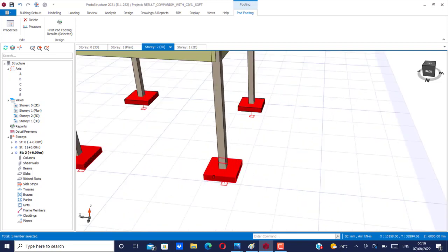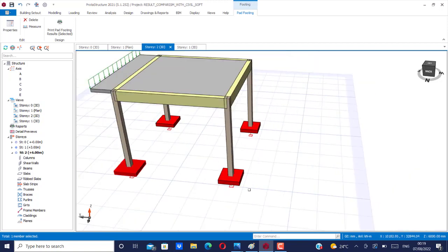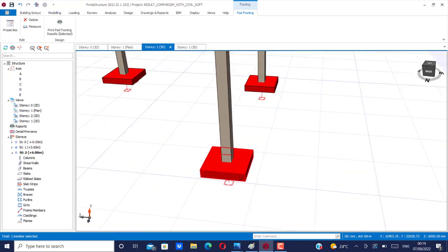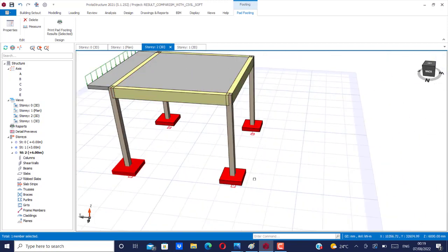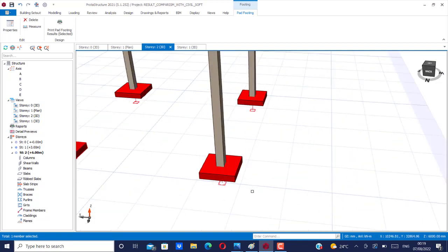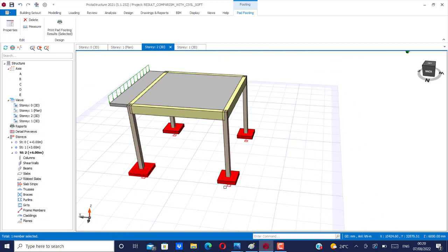So these footings, as these loads are coming upon them, it was observed that they behave in a certain way because of the way this load acts. These footings can undergo what we call bending. They can undergo what we call one-way shear, and then they can undergo what we call punching shear, which is also called two-way shear.